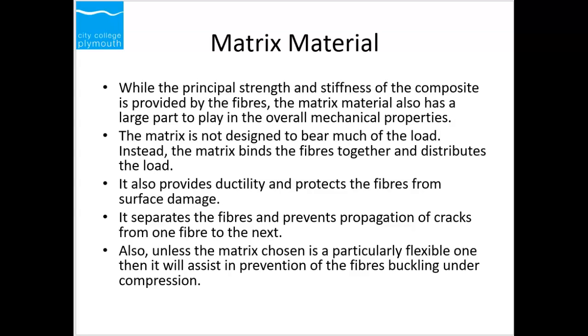It provides ductility and protects the fiber from the elements, surface damage, corrosion, and other things. It separates the fibers and prevents propagation of cracks. It also prevents the fiber from buckling under compression for certain types of matrix loading.